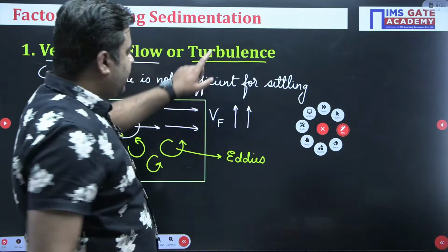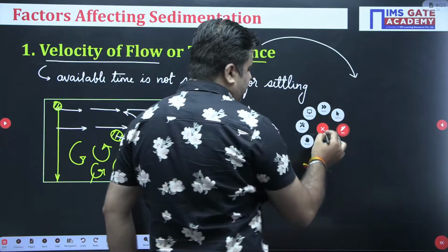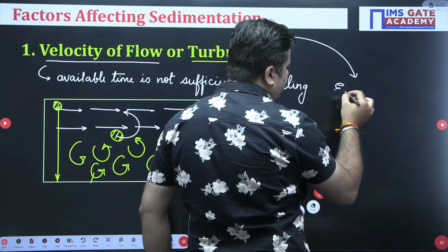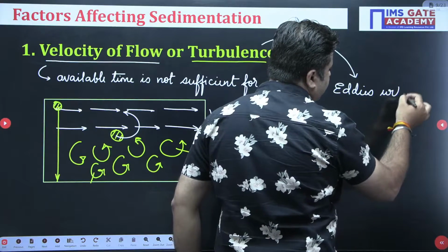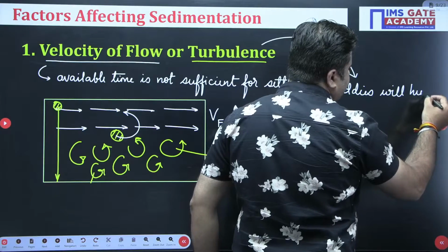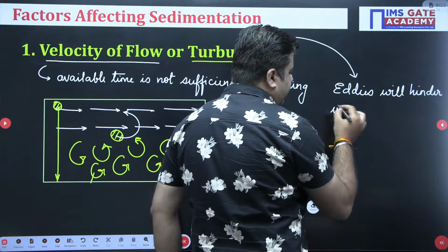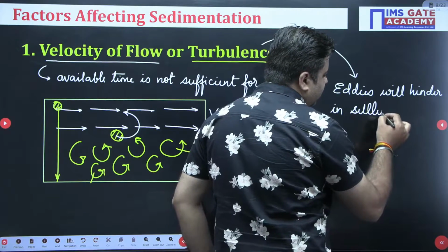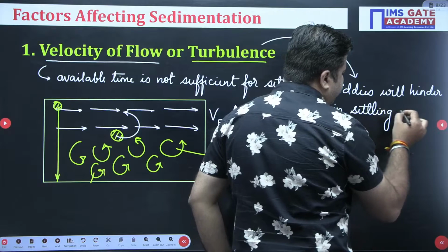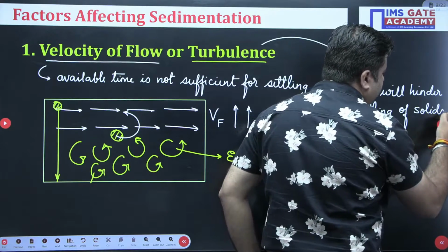Second, if high turbulence is there, eddies will be formed, and eddies will hinder the settling of solids.